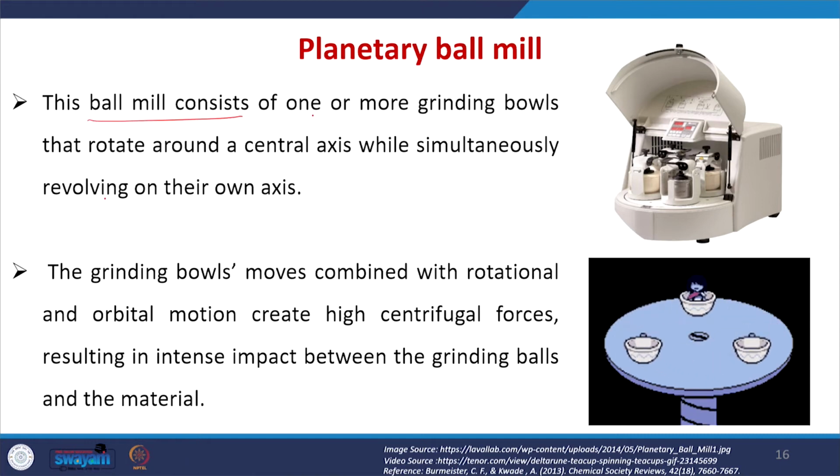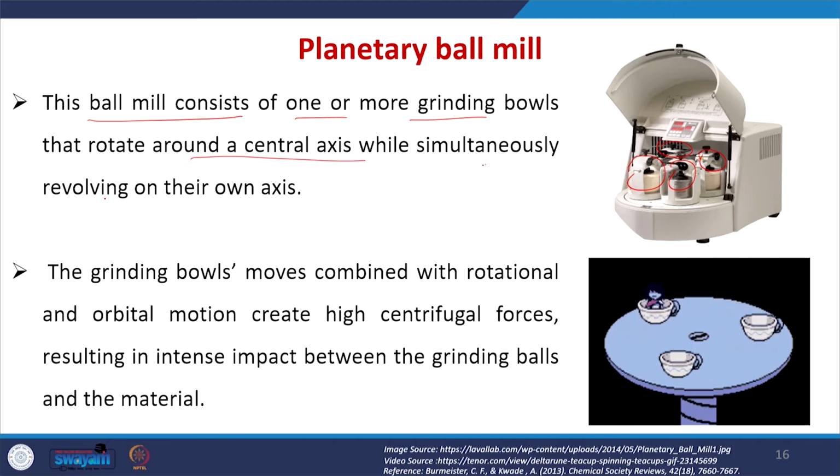This ball mill consists of one or more grinding bowls. You can see here there are many grinding bowls, and they rotate around a central axis while simultaneously revolving on their own axis. So, this base will be rotating in this direction and the bowls will rotate in the other direction. You might also have played during your childhood this cup and saucer ride. It is similar to that.